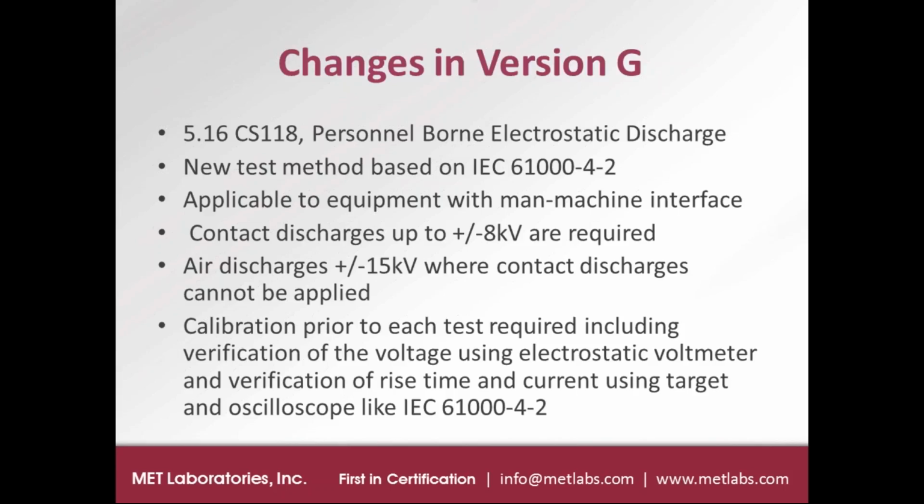target, they call it, which is a small metal disc that has an array of resistors around it that connect it to a Faraday cage. So when you discharge to the center of the target, and that target also has a coaxial output on it that gets connected to an oscilloscope, you get a controlled measurement of the current that's generated. You can measure that current waveform as well as the rise time and other parameters with an oscilloscope.